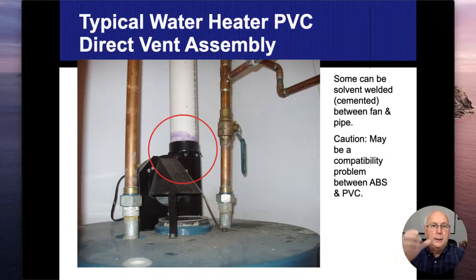I know I found a video, and I lift up on these things just to see if they are secure in there. I mean, I do have a fan that's being blown on there. If it's loose and not tight around it, then I'm going to roll the dice and take a chance of carbon monoxide being blown into the building. But more so, it's the other way around. I don't want somebody sending me a video saying, why didn't you tell me that this thing's not connected? So I just lift up on it and make sure the pipes are secure.